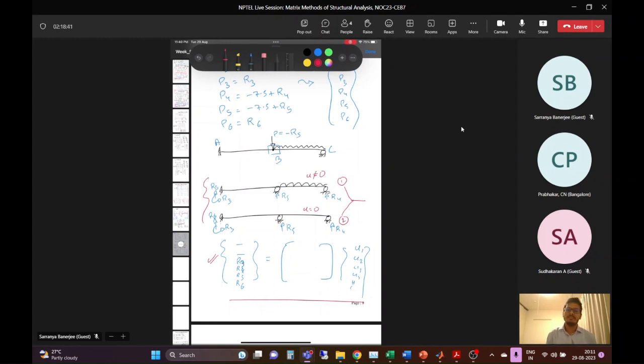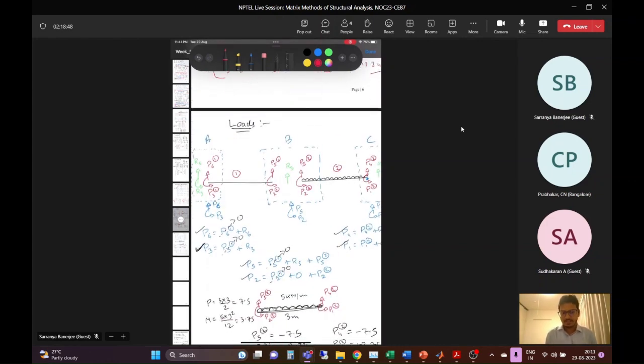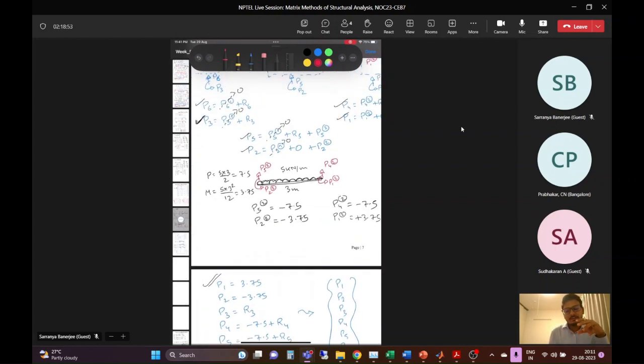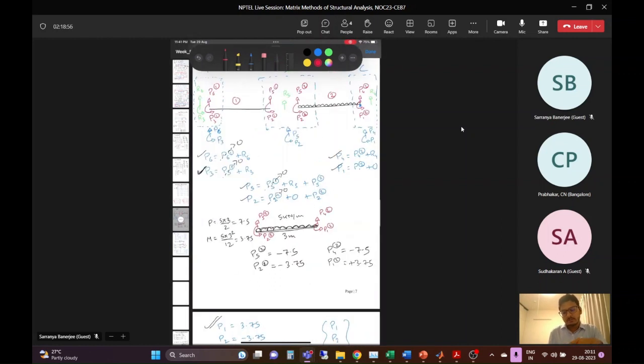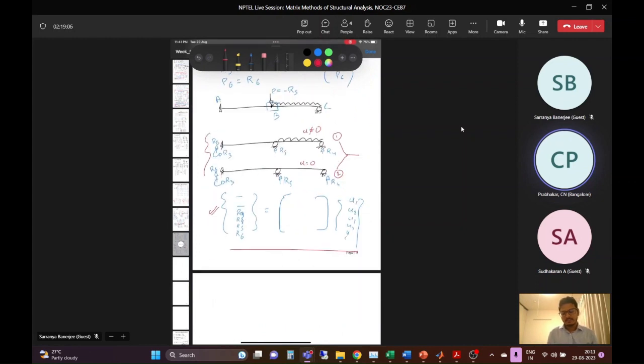In my opinion, for the timing, if we just focus on whatever we have discussed today, we should add the equivalent loads on the joints to find the final joint load, adding the equivalent loads and the reactions. Then that would be a proper definition of this unique beam problem. In the final equations, you are going to get R3, R4, R5, R6, the reactions.